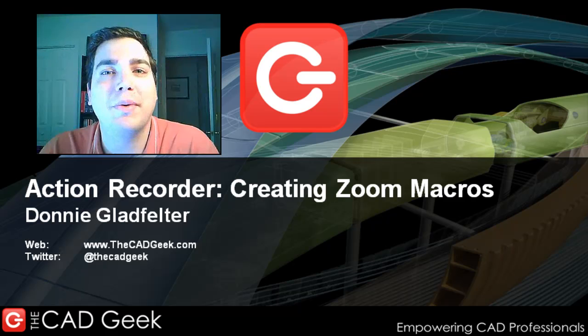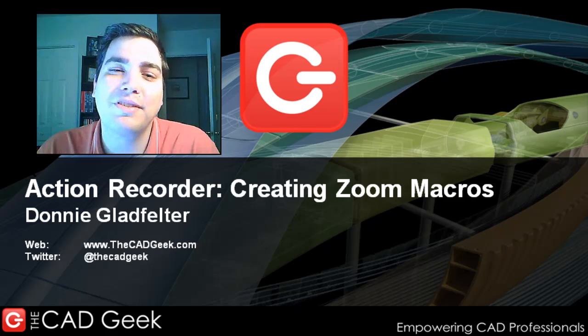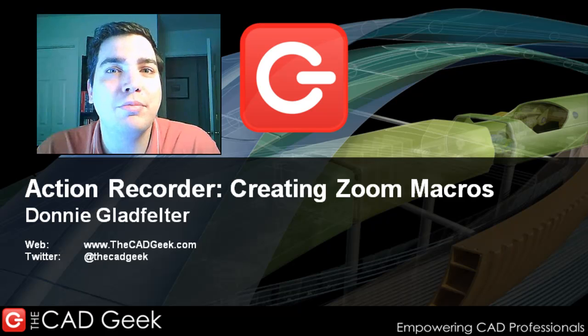Today what I'd like to talk about is how we can use the action recorder that we find inside of AutoCAD 2009 and AutoCAD 2010 to create zoom macros, similar to the ones that you might find inside of Civil 3D. And so by zoom macros, what I'm talking about, once again inside of Civil 3D, you're able to type things like ZP to do a zoom previous and ZE for zoom extents and so on down the line.